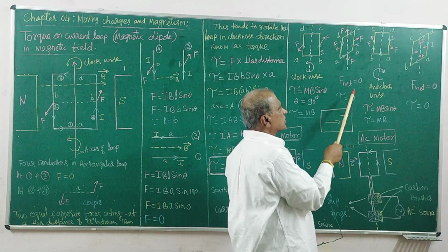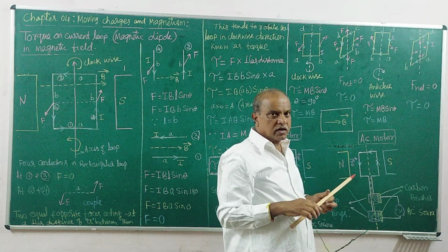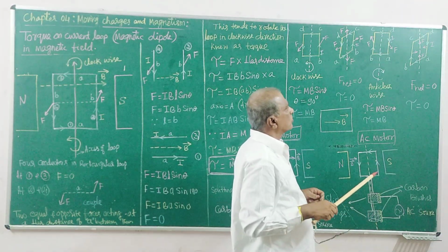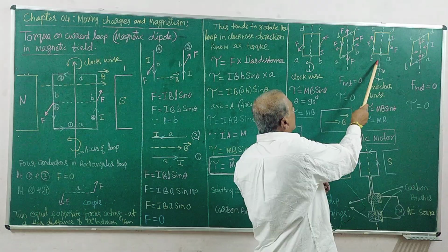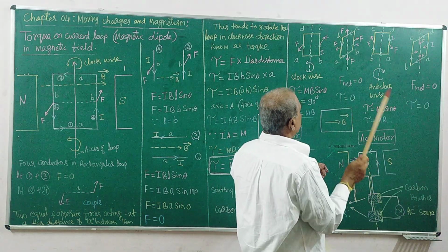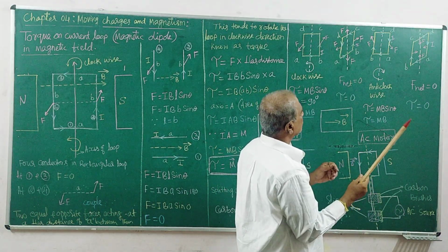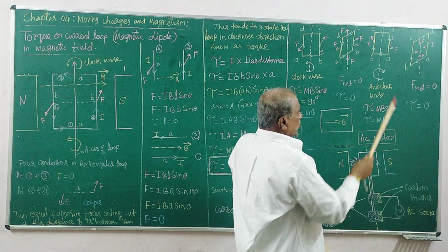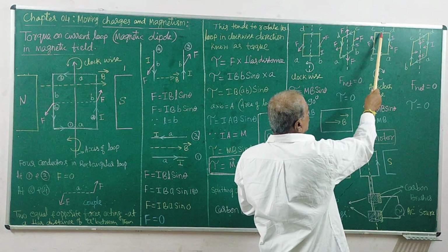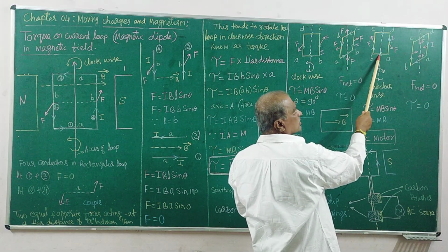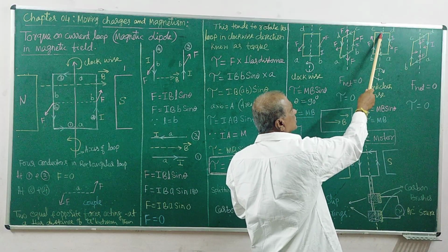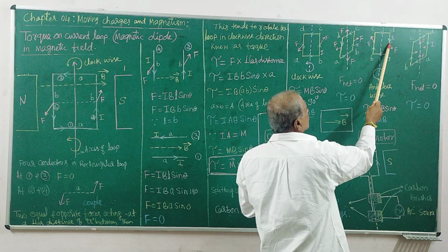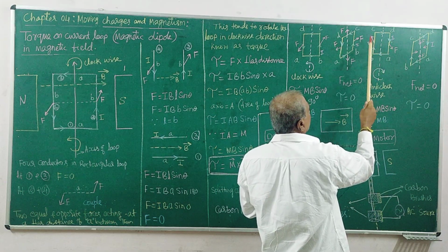If the net force is 0, it means the torque is 0. Torque is a result of net force by all the conductors. But in this alignment, it is rotated, left becomes right, right becomes left, and the current direction changes. Do the same calculation for these 2: the magnetic field and the lines are the same, so no forces at these conductors, but here forces are exerted because perpendicular.